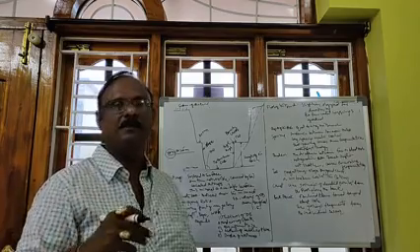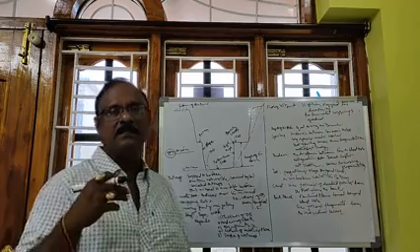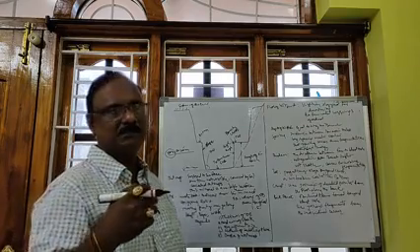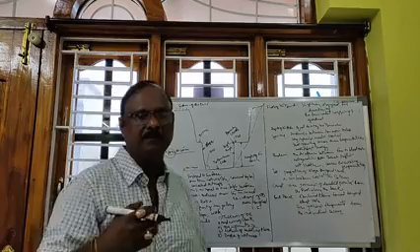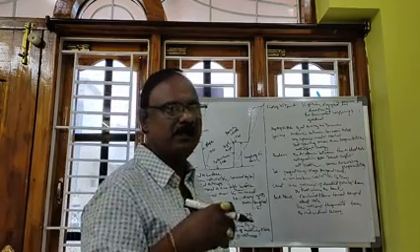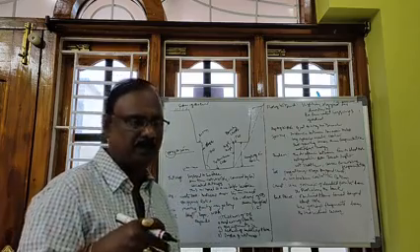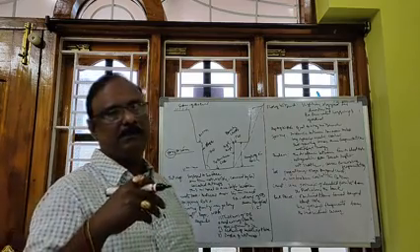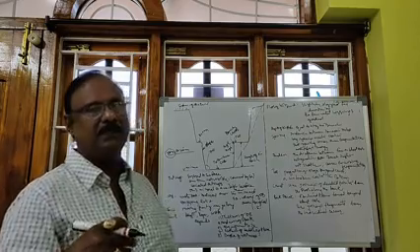Suppose the mineral is available at 50 meters and the height of the bench is generally 10 meters, then 5 vertical benches are needed to touch the mineral bed.